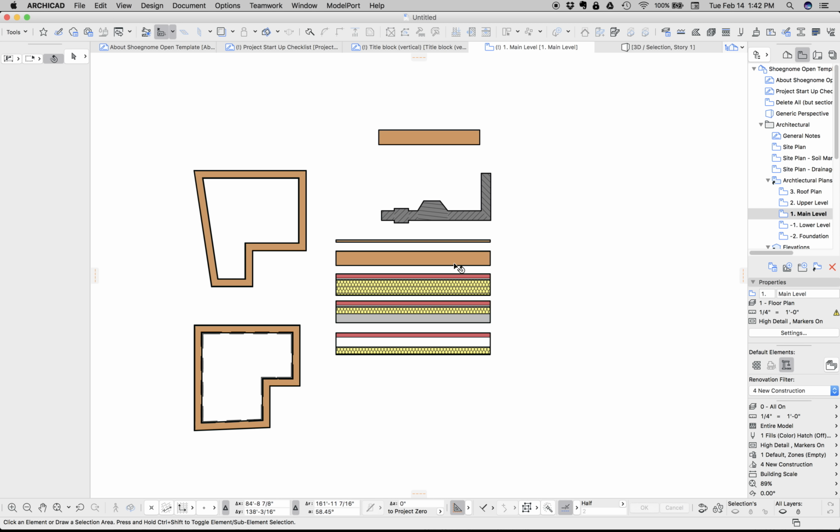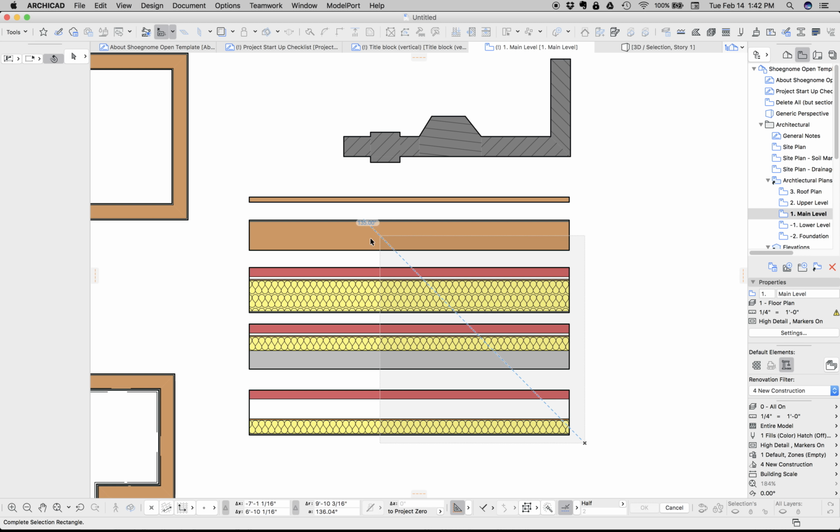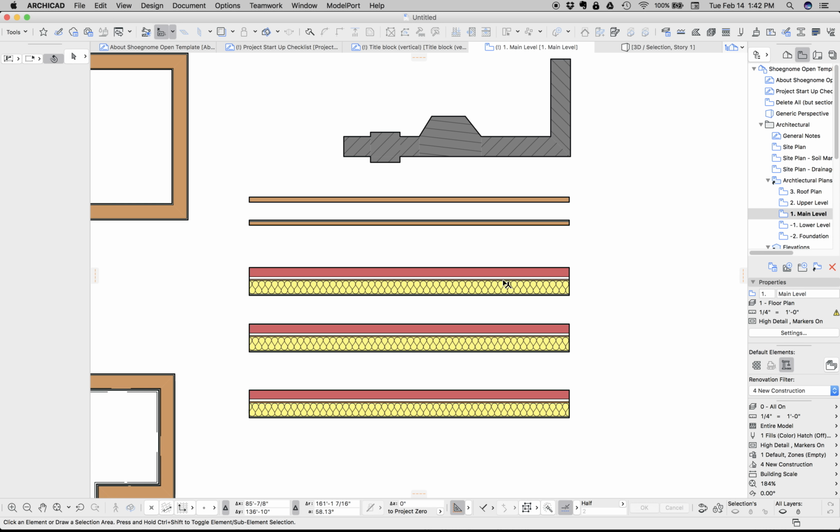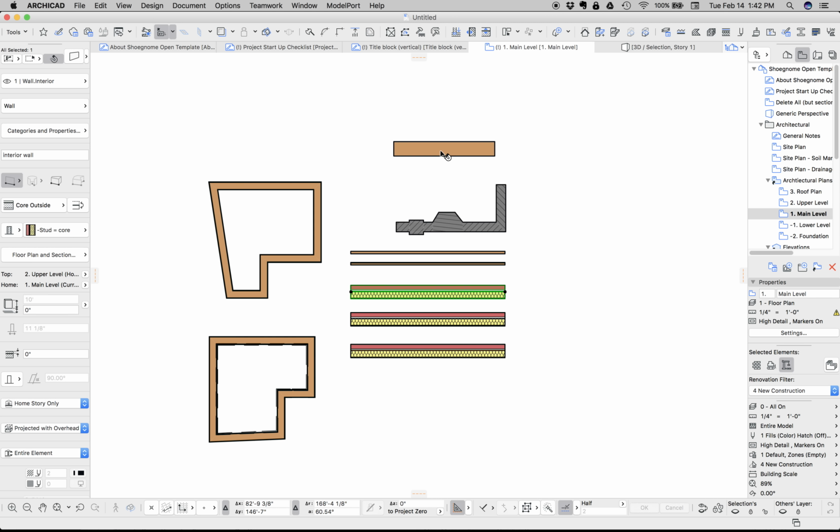But let's move on. The next thing I want to talk about is these walls and what's going on here. Up here in the wall tool, there are a couple ways to make walls. You can make straight walls, curved walls, trapezoid walls, and polygonal walls, so any shape you want. Trapezoid is kind of cool because you can make walls that, in plan, have different widths at the start and the end. I rarely use that, but where I do use it often is to create walls that are odd sizes and the same size at both ends.